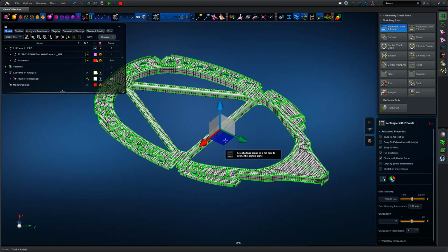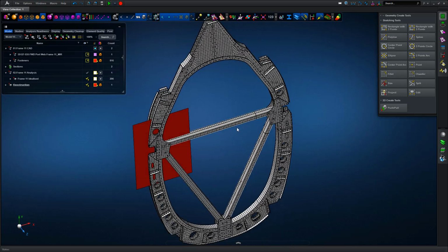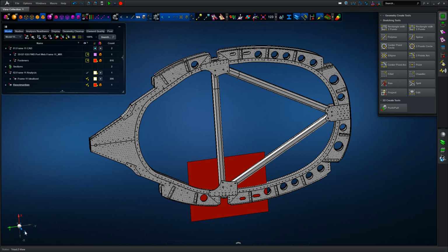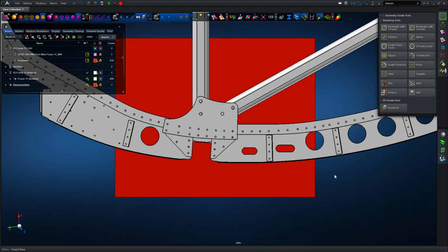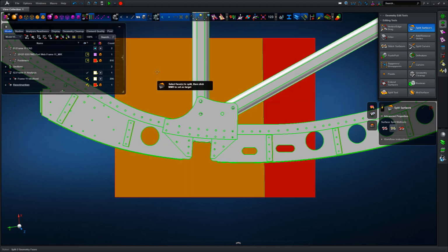So first of all, we're going to use some of the sketching tools to just cut or chop, for want of a better term, a portion of the original assembly definition out to create a region of interest assembly and control that using whichever means we need to within Apex. So first of all, sketching a surface normal to the cut. So once we've got that, we're basically splitting this surface in a manner which will allow us to cut the overall grey assembly shown on screen now. So if you just bear with me, and the cuts will make sense in a moment.